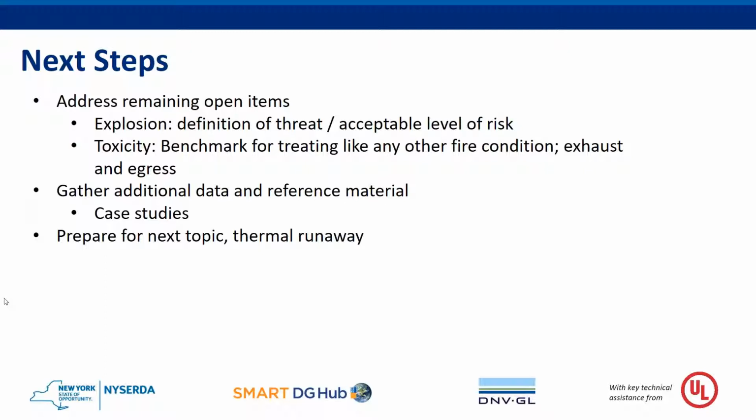All right. Is there anybody else who would want to elaborate on that? This is Jim from UL. I'll just say that our concern is, of course, anybody can do testing if they've got appropriate training and equipment. Whoever's going to be doing anything beyond the cell level, the 1973, is going to have extensive equipment in terms of calorimetry and all that other good stuff, and be certified to use it. At which point, hey, go for it. But we need to make sure that just because somebody can do 1973 doesn't automatically bless them to do the 9540A large-scale testing. They have to have the appropriate equipment and training.